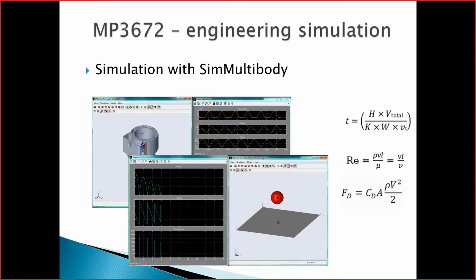It really does, but it can lead to a penetration. What that actually means is, when you look at the material, you'll see that material has gone through to the other side, even though the system says everything's fine. It's not fine. However, if that penetration becomes too large, the system becomes unstable. As it becomes unstable, it will allow nodes to pass each other. And that is where we've got to try and tune it.